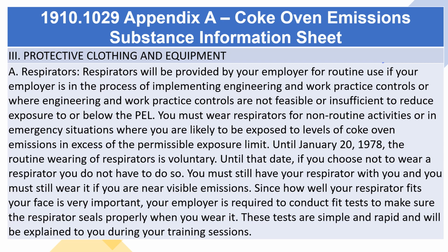Until January 20, 1978, the routine wearing of respirators is voluntary. Until that date, if you choose not to wear a respirator, you do not have to do so. You must still have your respirator with you, and you must still wear it if you are near visible emissions. Since how well your respirator fits your face is very important, your employer is required to conduct fit tests to make sure the respirator seals properly when you wear it. These tests are simple and rapid and will be explained to you during your training sessions.